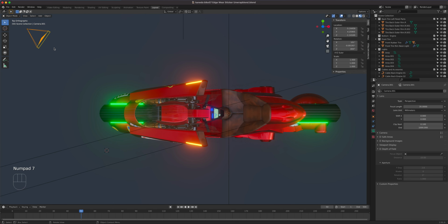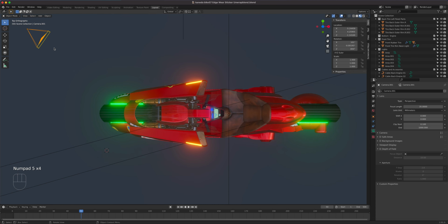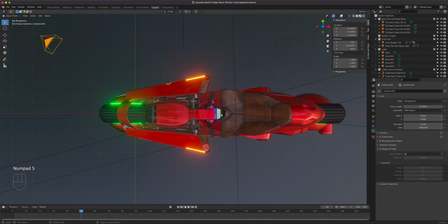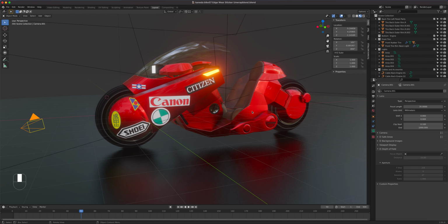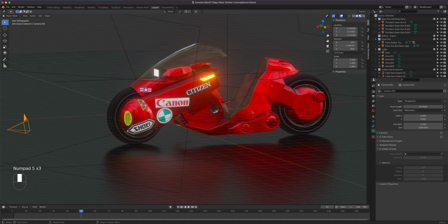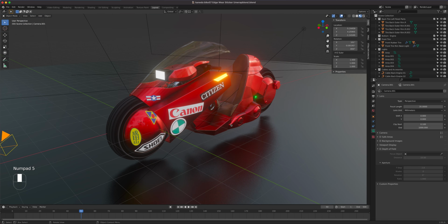You can also look into an orthographic view. If you press number 5, it changes from perspective, which has depth, to orthographic, which is flat. So number 5 on the numpad. A lot of new students freak out over that one. They accidentally press it and then they go, hey, this looks like one of those isometric games. Yes, it is. 3/4 view, 45-degree angle. So press number 5 and you get what the human eye would see.